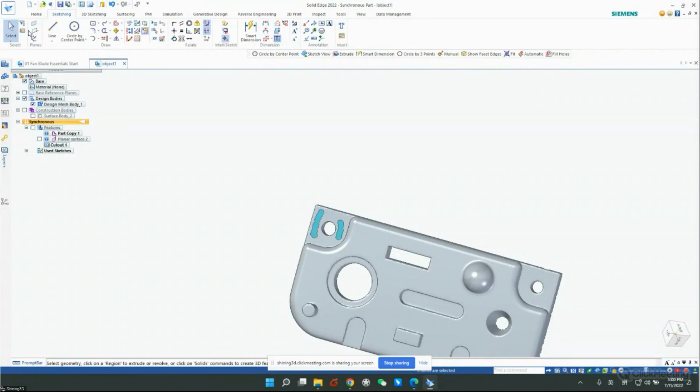You don't really need to go through the full reverse engineering step if you don't need a CAD file for your output. So I recommend you use this function if you only need 3D printing, or if you only need pure mesh data for your output. But if what you need is the CAD model, you have to go through the full reverse engineering process.